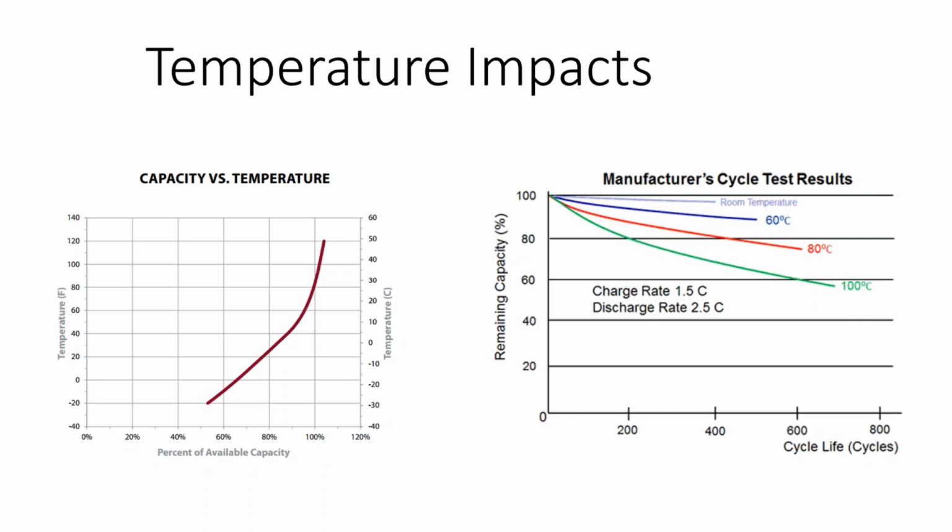In the wintertime, if my battery is at full voltage and I still have this surplus electricity, I want to turn that heater on and heat up the concrete floor and the thermal mass in my battery box or battery room so that, overnight, the temperature of that room stays higher than freezing. Put that inefficient surplus energy to work.